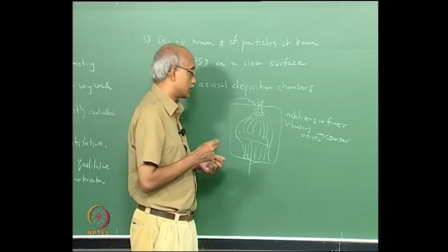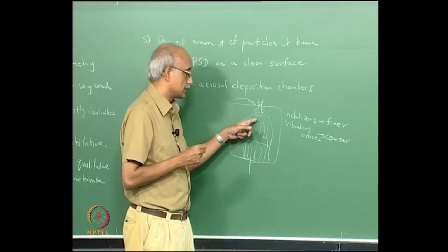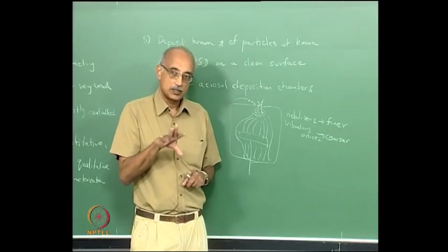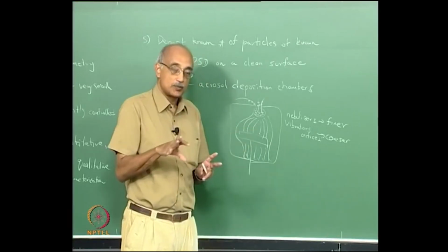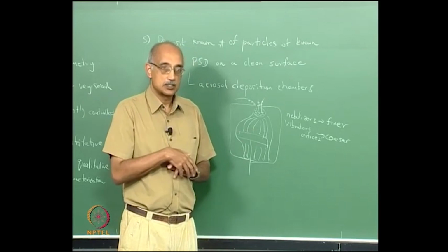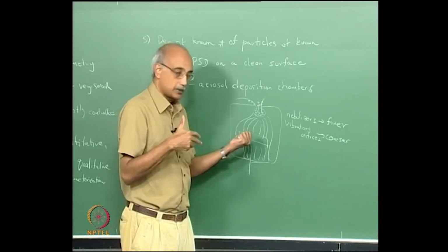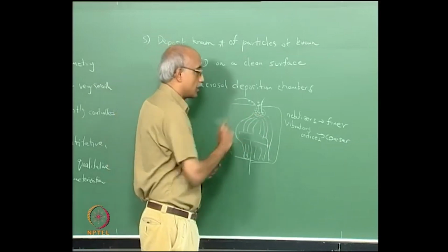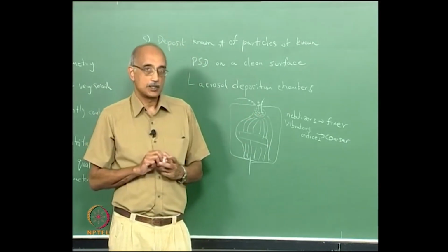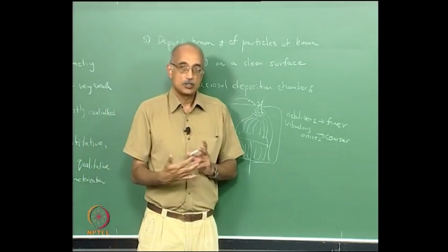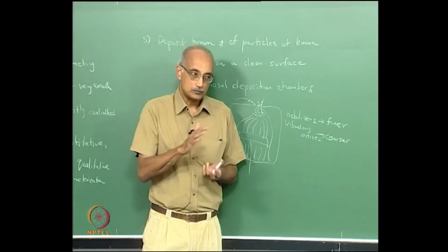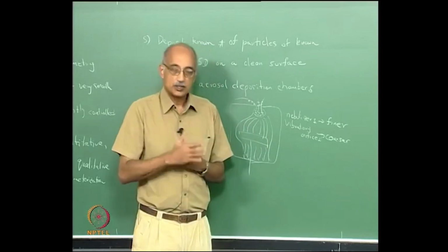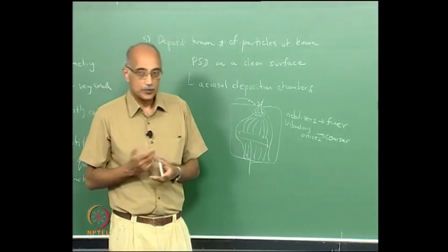You have to ensure that particles when they leave the orifice are being delivered at a constant velocity, because especially in the case of larger particles, the velocity determines the impact potential to the surface. So, the output from the nozzles should be tightly controlled in such systems in order to ensure that the particles are delivered to the deposition surface in a repeatable and reproducible way.